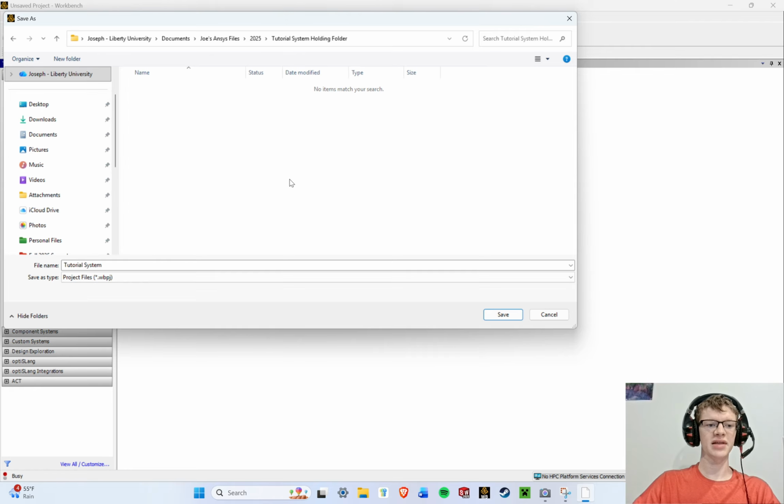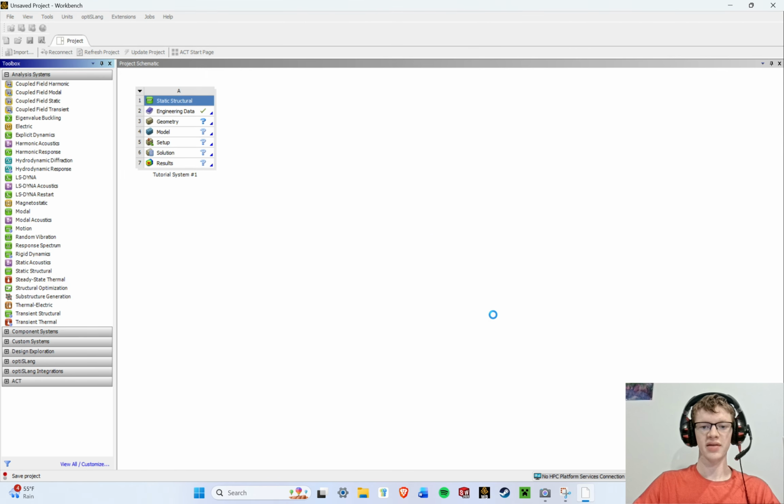And the reason that I put this in its own folder with no other projects in that folder is that I know this is going to create that .wbpj file that I can open, as well as two other files, and I don't want those to get confused with other projects that I have, so I give it its own unique folder. Then you can click Save.